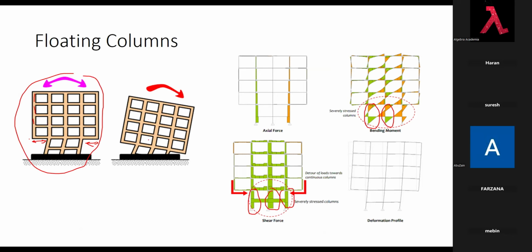So if you are designing this kind of building considering the seismic effect, for axial load it is easy, but if you are considering this seismic horizontal load, you need to increase the column size drastically and the reinforcement drastically, then only the building will be safe. Otherwise the building will collapse more easily under seismic load.